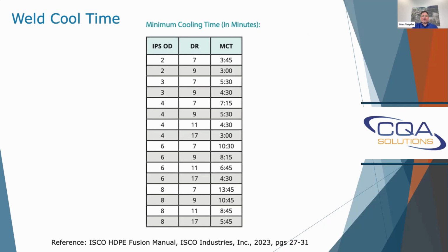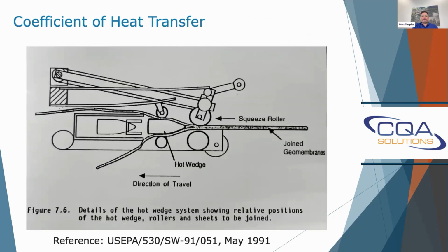I don't know if there are any studies on it. I haven't found any. But with extrusion welds, you'll see the installers will sometimes dump soapy water on it right after it's welded so they can start their vacuum test. That's artificially cooling down the weld substantially, and it's going to damage the weld and crystallize it and potentially lead to failure in the future.